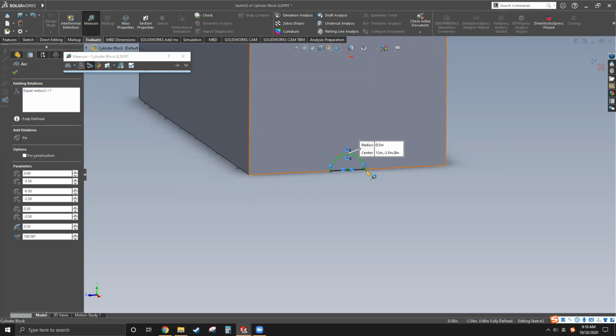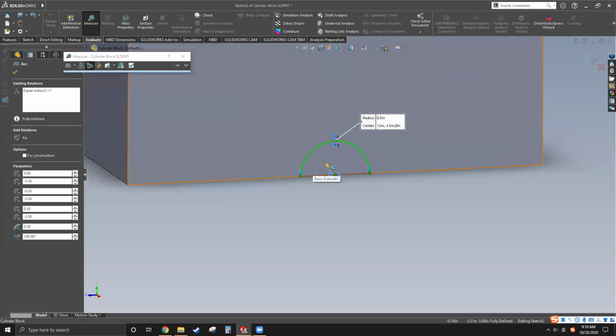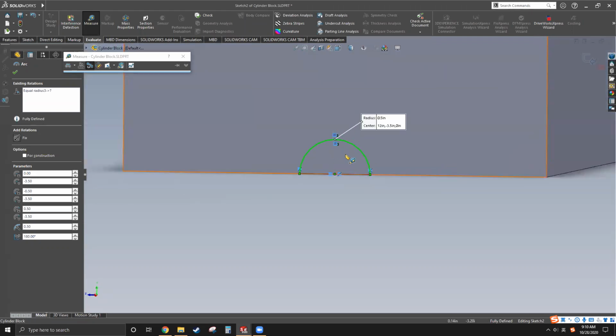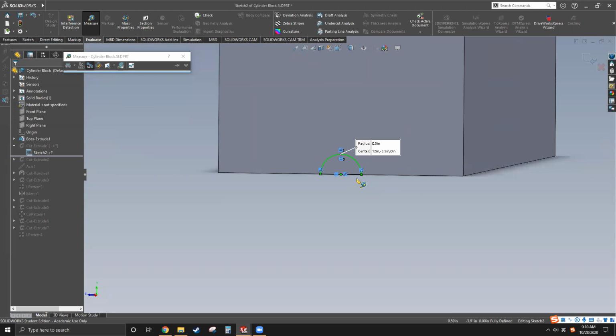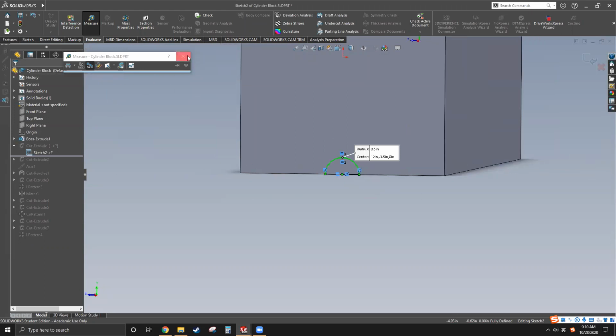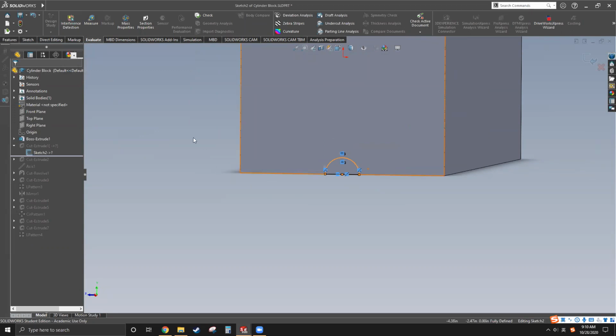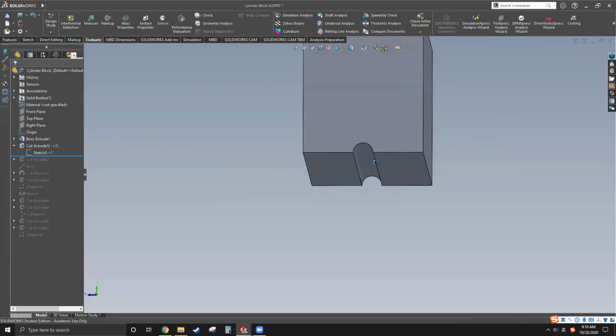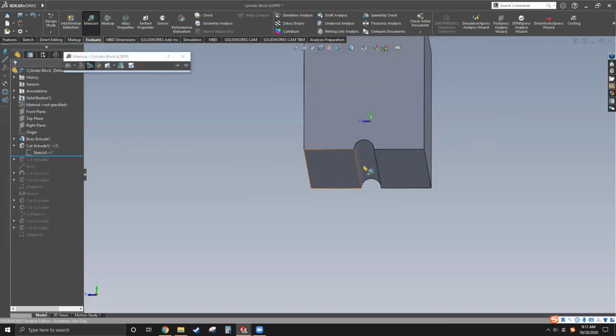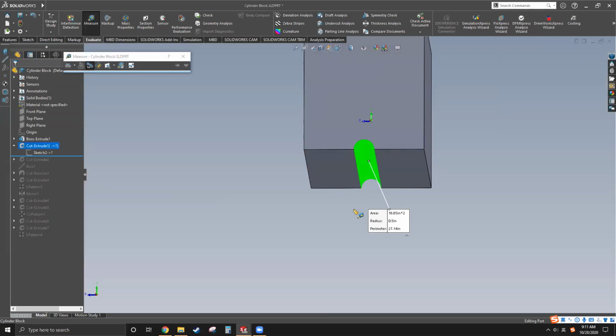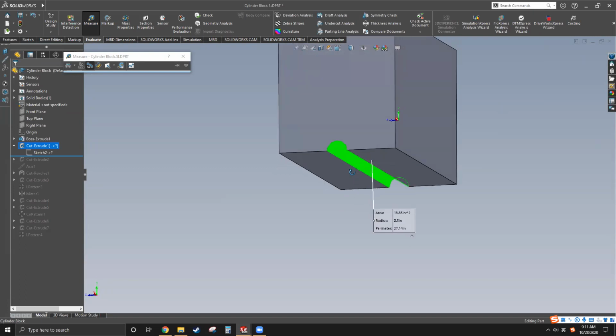Oh, sorry. Make the semisphere that has a radius of 0.5 inches, and after that, extrude cut all the way through, so your groove can go all the way through the bottom. And let me know if you've done. Let me know in chat if you complete this feature.